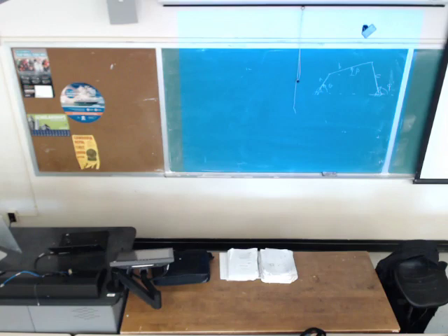On the outside, you have these two. You would like to have this desired task. When this guy is at the location of x1, showing x1, this guy should show y1. And when it goes from x1 to x2, you would like this guy to move from y1 to y2. So we would like to design a 4-bar mechanism such that it generates this desired function for us. As I said, the correlation between x and y is given, not between theta and phi.